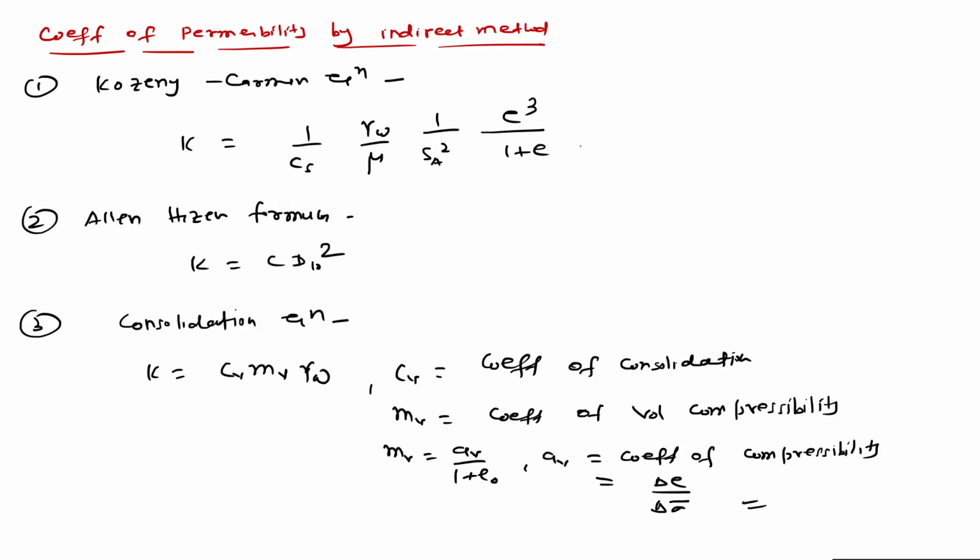Now, question number 14. A strata of 3.5 meter thick fine sand has a void ratio of 0.7 and G is equal to 2.7. For a quicksand condition to develop in this strata, the water flowing in an upward direction would require a head of.